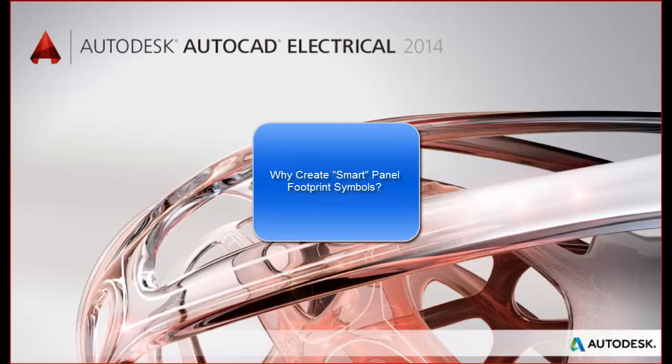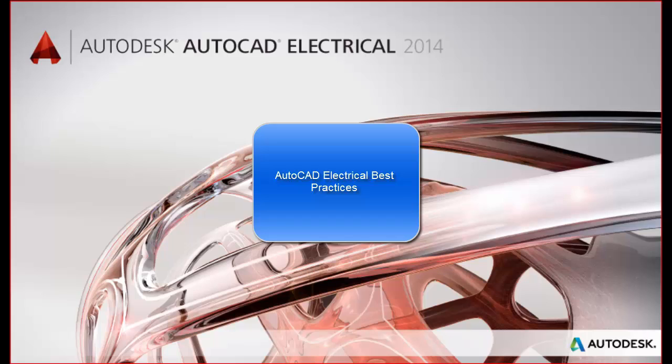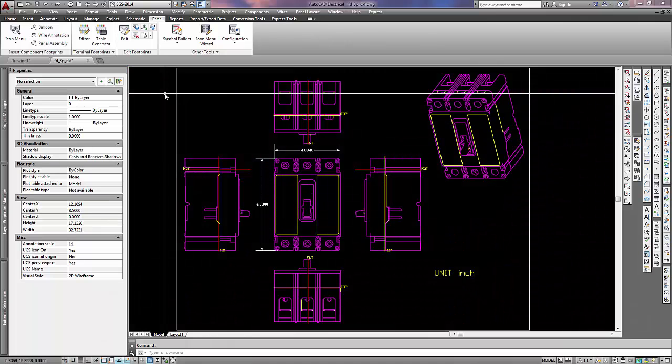Smart symbols provide a designer the ability to add intelligence to a design. This enables the extraction of data from completed designs for bills of materials, for tags, for charts. It ensures that all parts will fit, and much more. It is a best practice to create all your symbols geometry, including text, in model space. This allows you to create your geometry at full size and use the viewport to scale it to fit on paper. A new symbol can be created from using existing geometry, an existing block, or by launching Symbol Builder without selecting any objects and building your symbol from scratch.